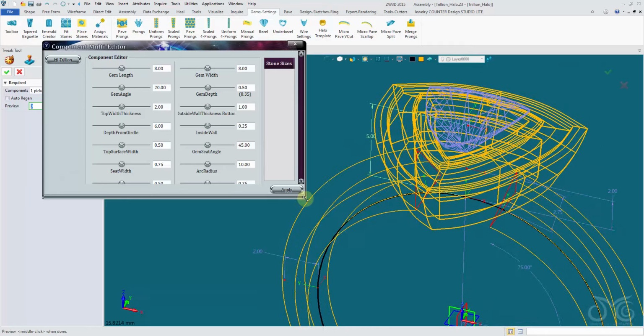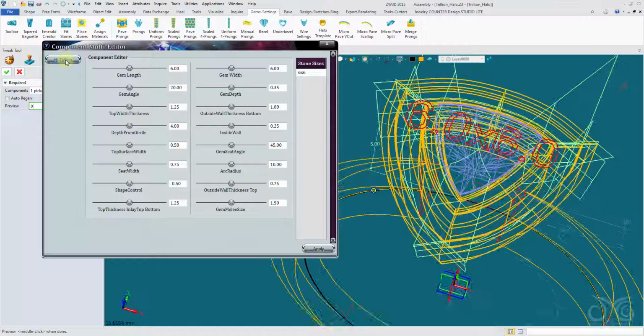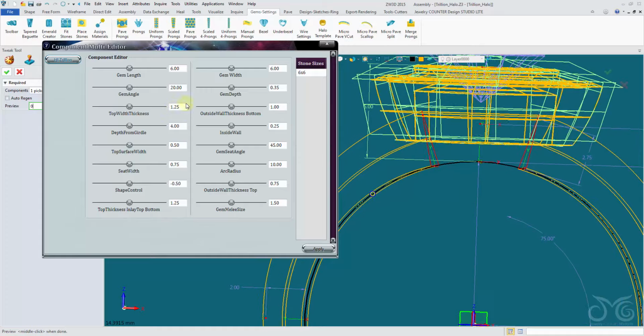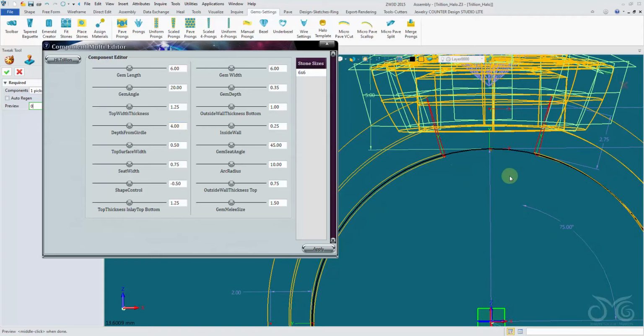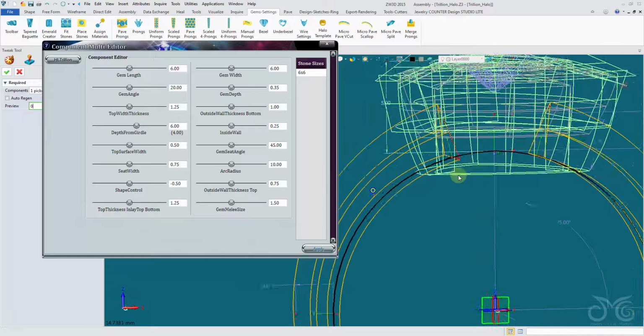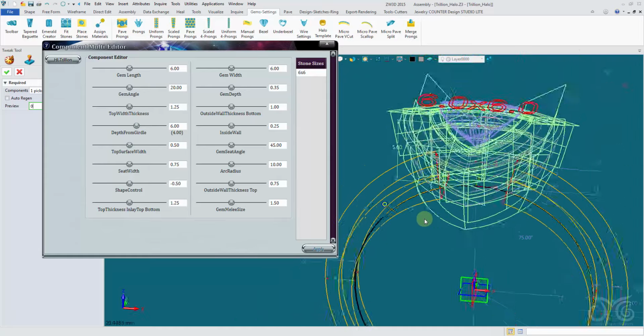We're in our tweak, so we can make our tweaks from within here. Remember, activate it from there. Okay, our preview goes funny again. The one change I do want to make though is drop down my depth from girdle, because I want this to come down, cut through here, come below into the ring finger. So let's drop this down. Depth from girdle, just say 6, because we're going to be trimming it out anyway with the ring finger sketch. Okay, I'm going to confirm this operation here.